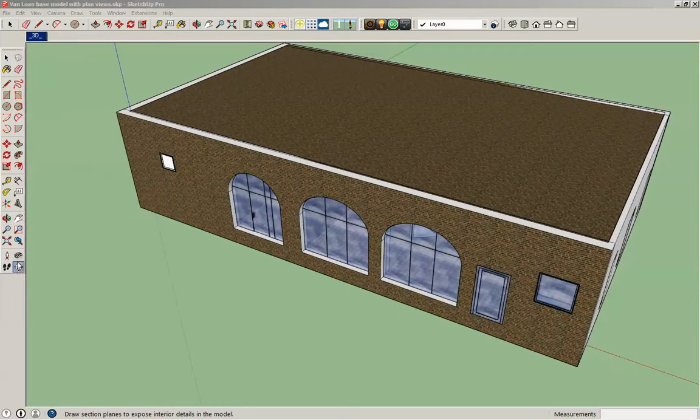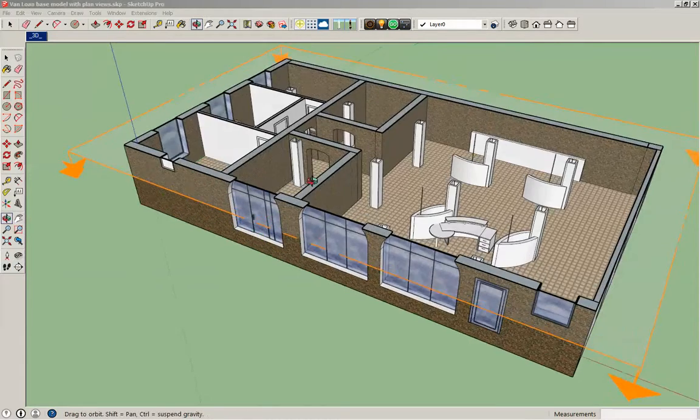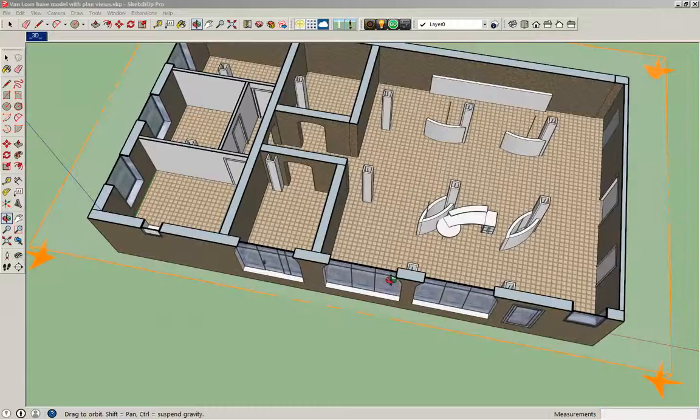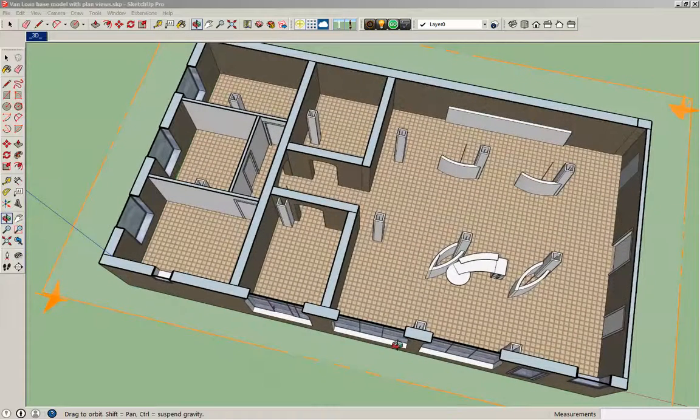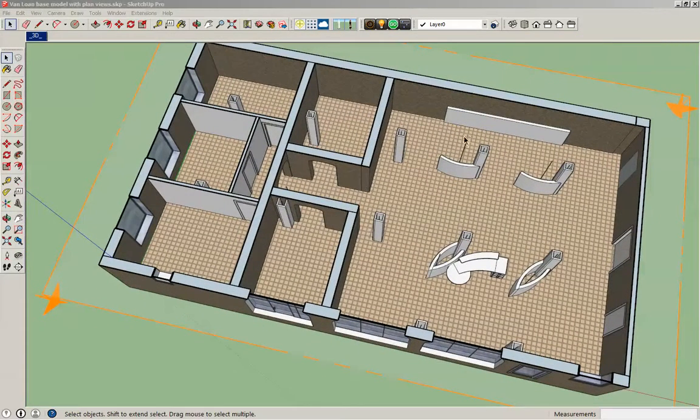I'm going to click the section tool. It's facing down, and of course that's handy. I don't want it to face up, so if I want it to stay facing down, I can hold down Shift to lock that inference, and then click high up on the wall to cut away the model. And as I might have mentioned in class, this is a really handy view to have when you're space planning.